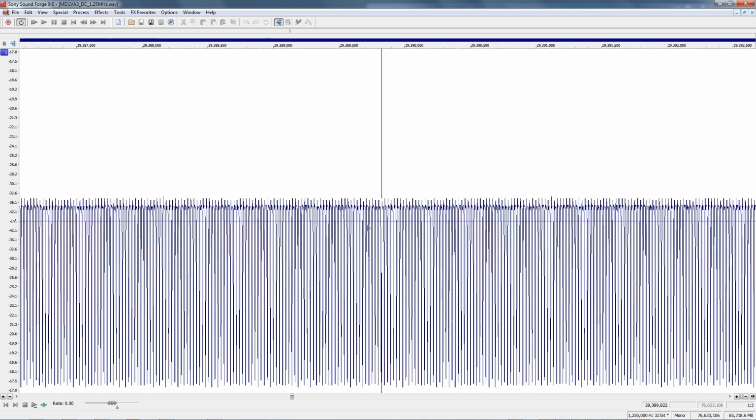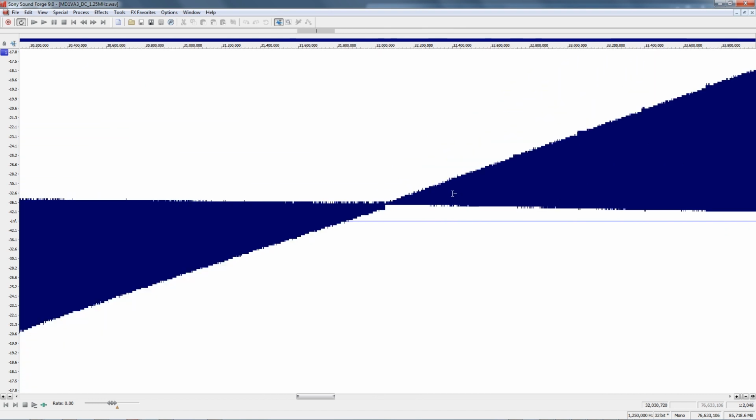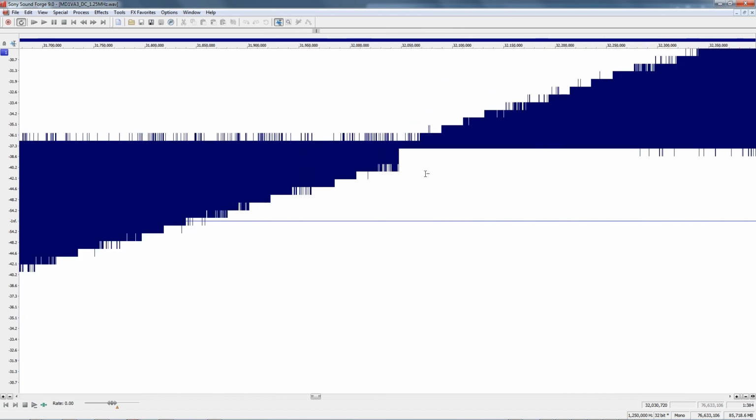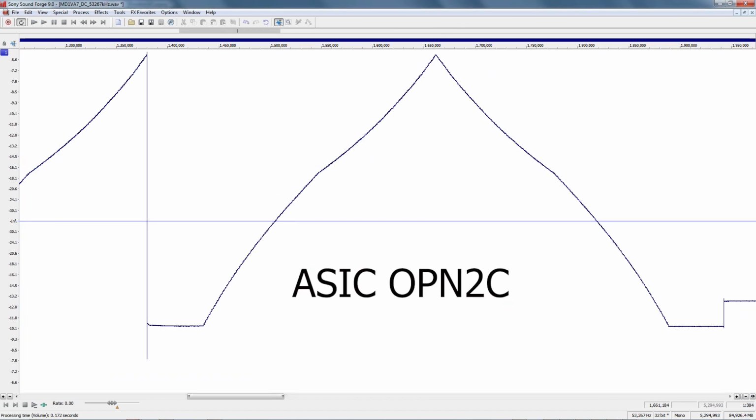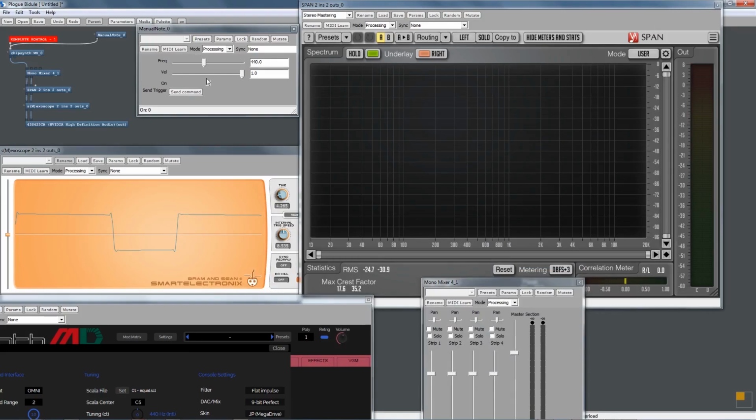Specific DC tests are done also to pick up the audio directly from the pins using a DC coupled scope. This highlights the famously non-linear DAC of the OPN pretty well. An ideal 9-bit DAC would sound like this on a decaying sine wave.